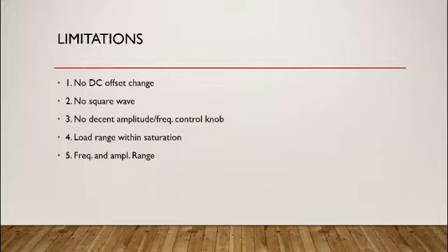The second thing is there's no square wave. This is because of how we designed it. The third thing is there is no decent amplitude or frequency control knob. We used a chip potentiometer resistor on the PCB, and it is controlled by a screwdriver.